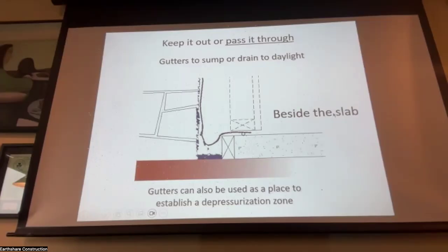With these gutters, if you're pouring a new slab in an old dirt floor, do they need to be pitched somehow? Is that complicated to achieve? If you're planning, like, if you have the washing machine running onto the floor, yes, you want the pitch to the drain. If your basement is dry, you can be perfectly level and have wall-to-wall carpet on it. So this depends on how well you can dry out the basement, or the problem. Be sure that you're not going to have mold or water that will ruin the floor. The diffusion point, the diffusion separation from the slab.